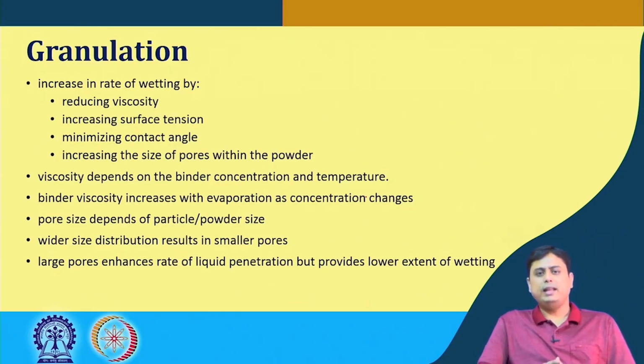Quite naturally, if we increase the surface tension, we can have an increased rate of wetting, and by minimizing the contact angle it can spread over the particle surfaces very efficiently. Increasing the size of pores within the powder helps so that the liquid can quickly penetrate, because the larger the pores, the more easily the liquid can penetrate into those gaps.